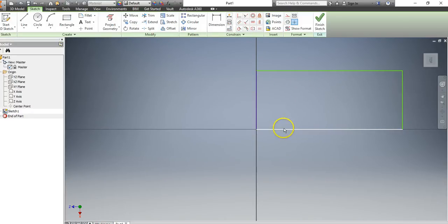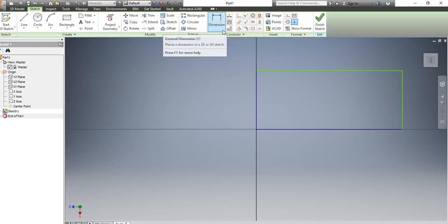These two lines, whenever you start a project, should be purple. That means that they are constrained to this point. If you don't see these two purple, and down here in the right hand corner, it's not in the screen, but it says there are two dimensions that are needed. You're going to look at this in the right hand corner to make sure that you have dimensioned this thing fully before you take it to the drawings.